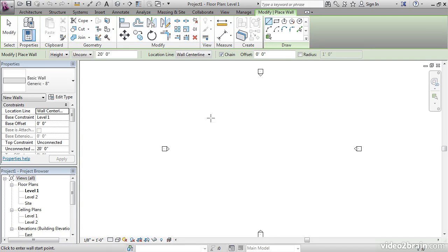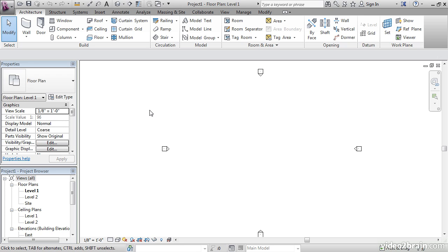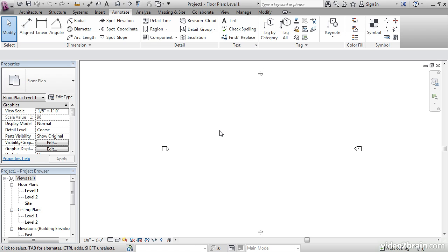In Revit, once you start a command, the interface will change to give you tools to aid in that command. Another thing that Revit adds is called the Options toolbar. You'll be hearing me say this throughout the course. Keep your eyes on the Options bar. Hit Escape a couple times. Or you can click the Modify button to release yourself from the command. In Revit, you're always in a command in some degree. If you want to clear out from the command, press Escape or click the Modify button. No matter what tab you're on, the Modify button will always be there.